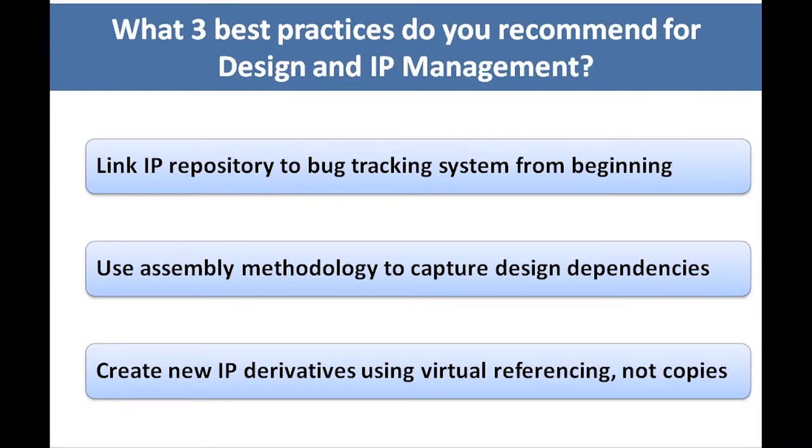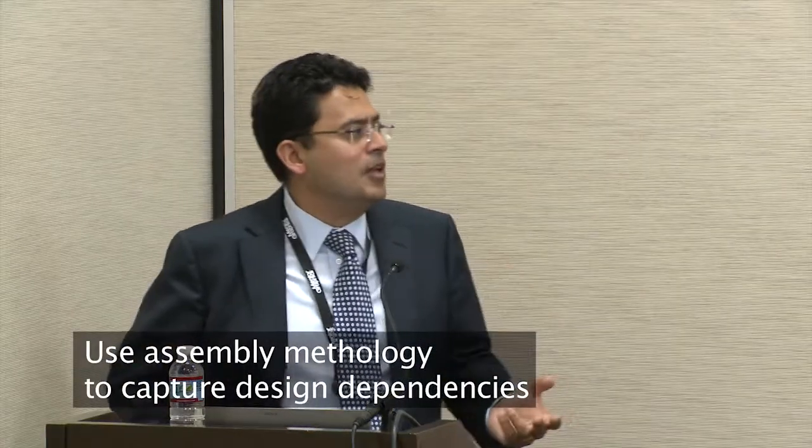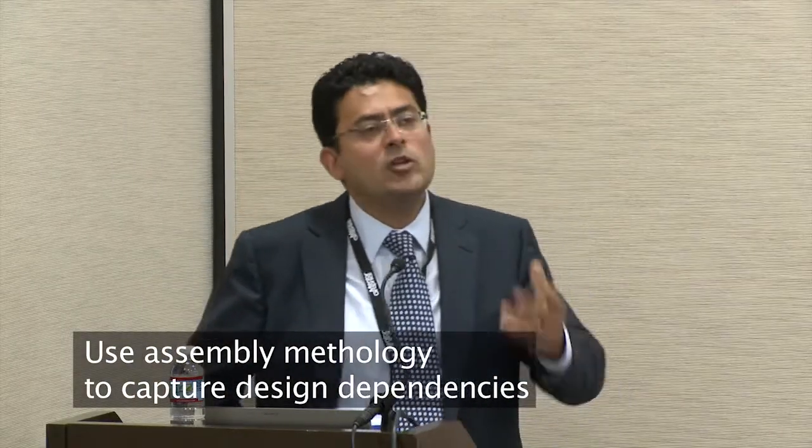So the best practices that we would recommend, the top one I would say, is link your IP repository to the bug tracking system right from the beginning, because bugs and bug fixes are actually represented in your data itself, and that binding is very important so you know what you've got. Use an assembly methodology to capture your design dependencies. When you put stuff together, use a methodology that assembles them, however you do your hookup, how you bring in your different releases. If you do that in an ad hoc manner, or through random scripting, you're not going to understand your dependencies. As a result, you're not going to know what you have in your chip, and you have to backwards figure out what was in it.